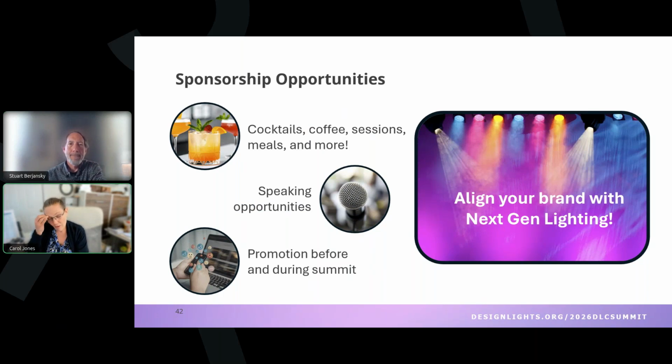It is a tremendous feature because you can get all the information digitally. When you're connecting to emergency with a DALI system, it allows you to do remote testing so that you don't need to get up on a ladder, and you get all the information that you need. As far as I know, there's not much available in the market yet. I mentioned before that the supply chain is getting better, so that is one of those things we do expect to see, but it's not prevalent yet, and you can tell by going to our database.